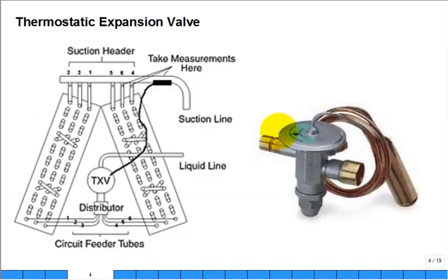Here is a close-up of that thermostatic expansion valve with that bulb, and the service technician can move it and place it, and then strap it on to the outlet of the suction line right immediately after the evaporator. These are fairly cheap, but they're well engineered. Little needle valve, and this diaphragm up here, sensitive to the temperature and pressure, moves it up and down. You have the same metering in the automotive air conditioning system.